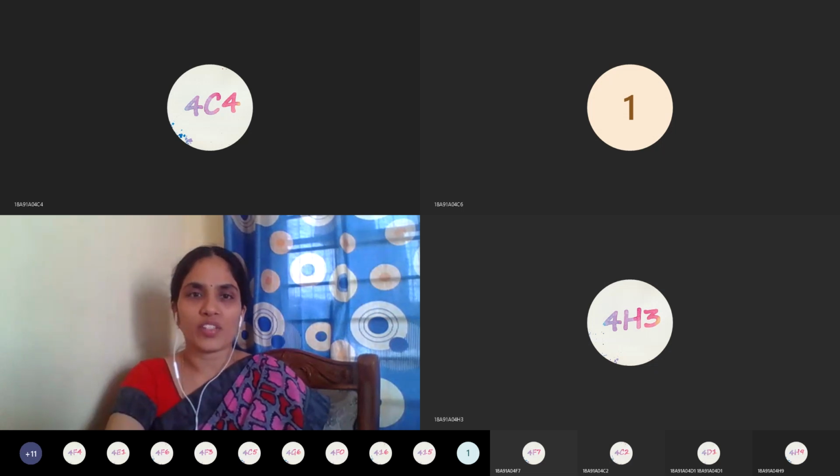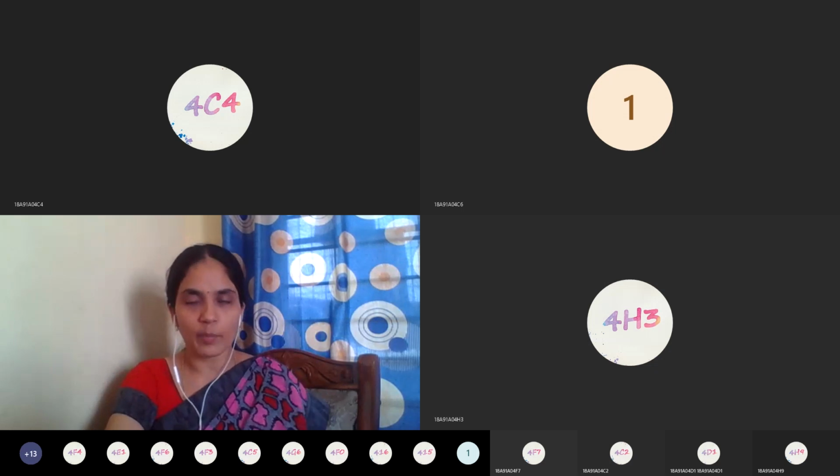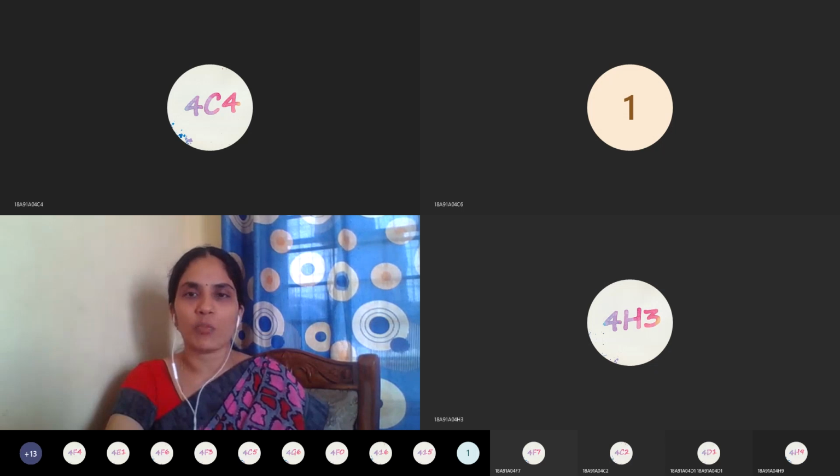Actually, in your syllabus, they mentioned the similarity of BFSK and BPSK because ASK is the least preferred technique because of its main drawback that it possesses amplitude variations. So either FSK or PSK will be preferred in general. That's why they mentioned it like that. But we have to compare all the three because you have studied all the three techniques. So after this module, you should be able to learn the comparison between ASK, FSK, and PSK in all aspects.